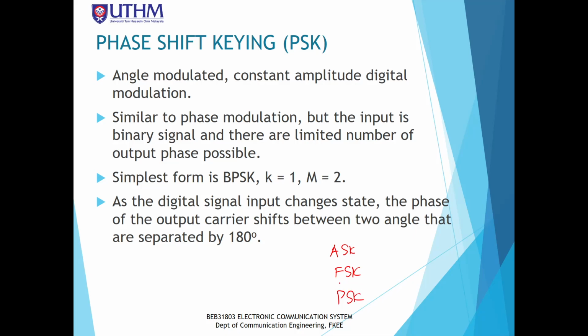PSK is a modulation process that changes the phase characteristic of the carrier in accordance with the digital input variation. And remember, all of these three modulation types, ASK, FSK, and PSK, have different types of variations of each modulation type. They have a big family.